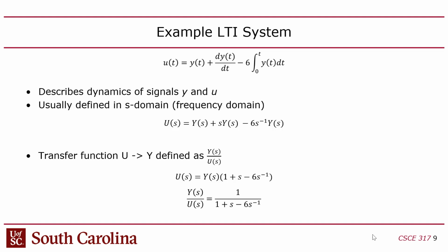All right, so you start out with a basic equation. If you guys have probably done this in circuits too, right? So you can do this for a circuit, an RLC circuit, or you can do this for physics. Newton's laws can be used to construct this type of equation. Just Newton's laws, basic physics equation. But generally, when you do that, it's just an equation. It's just the relationship between these variables. When you make this into a transfer function, that's when you are conceptualizing this equation as a transfer function, which implies that you have an input and an output. Does it make sense? In this case, there's just a single input and a single output.